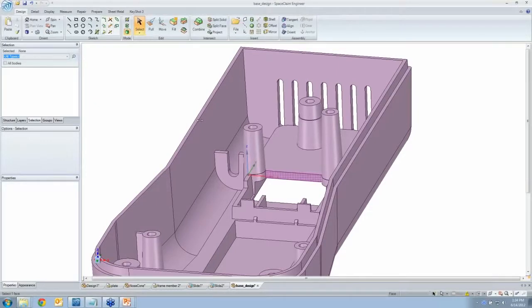One question that came in was in regards to point cloud data and just data from a laser probe. The format that we really need to get data in if it comes to scan data is an STL file. So if you have something that will turn your point cloud data into an STL file, that's really the way that you want to handle it. We'll take things like a text file of points and utilize those, but if you're talking about point cloud data, we really need a different format like an STL file. And to my understanding, there are a lot of programs that will convert point cloud to STL. So good question, though.